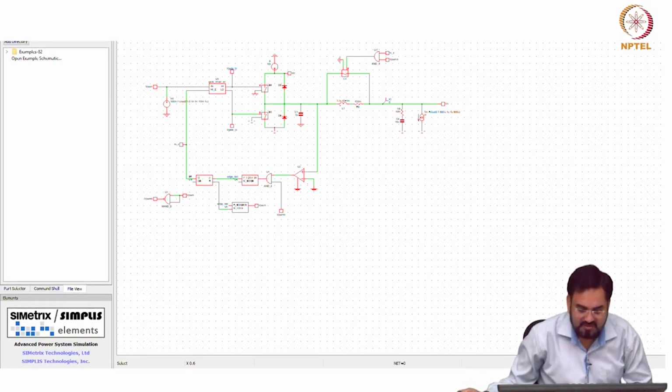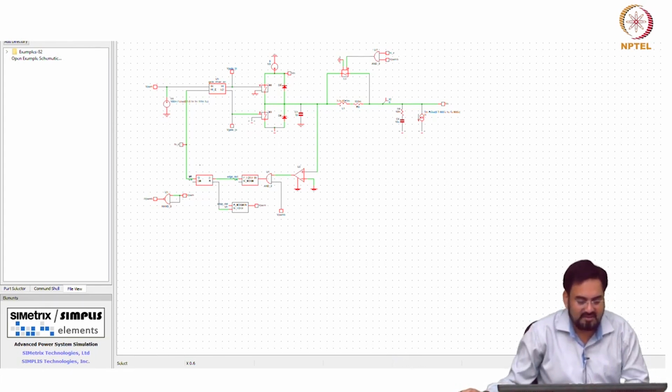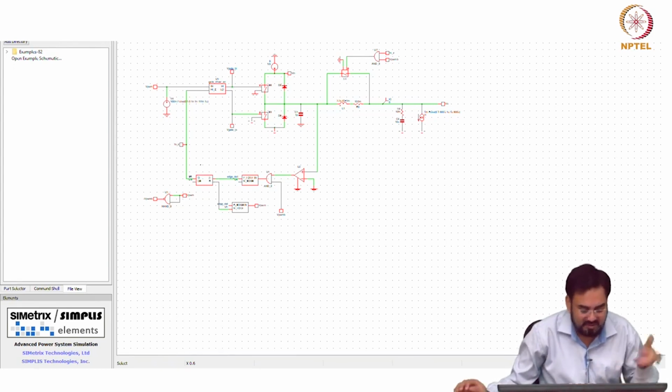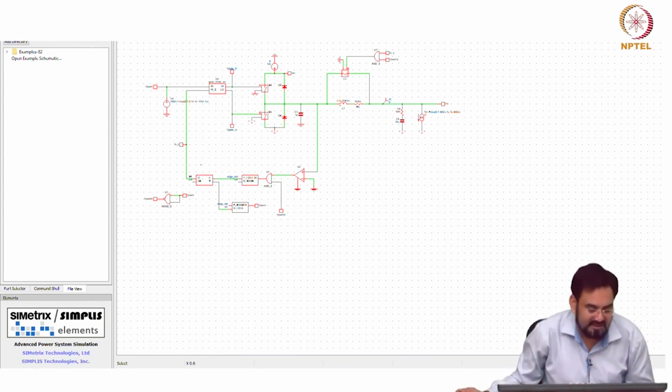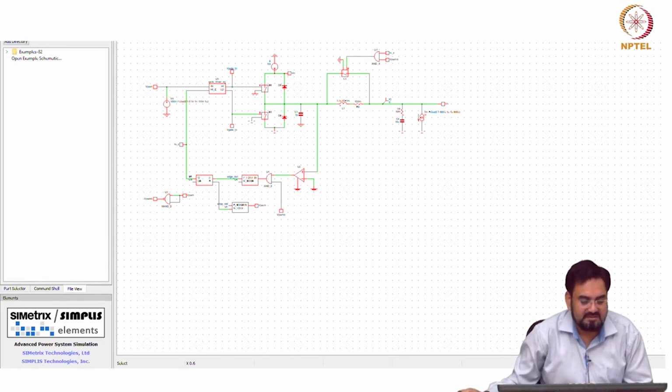So, this is my 0 cross, okay. Then after that I have a high edge detector and then a flip flop, and this is an SR latch actually, not the same D flip flop. As I told you, there could be different ways of implementing that. And then I have a high Z input here which disables the power FET. Okay. So, let me remove this.